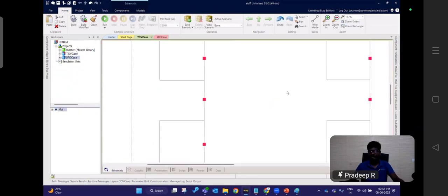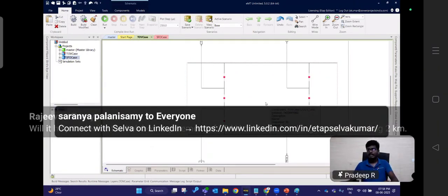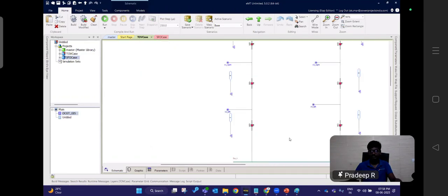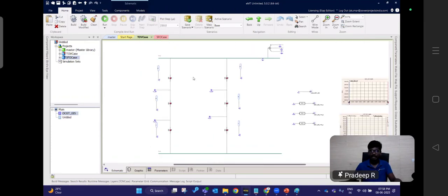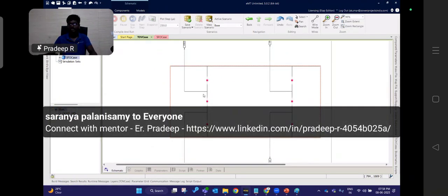Following that, this is my GIS. GIS usually will have more elements, like disconnector switch, switch, everything. But in this case, we will be modeling our breaker only, and that too only for opening and closing operation. Rather than that, we will not be modeling a detailed model. For protection purposes, we won't model. We will be modeling this breaker just for opening and closing action. Why? Because we want to do energizing, de-energizing, everything. So for that, my breaker must support opening and closing actions.